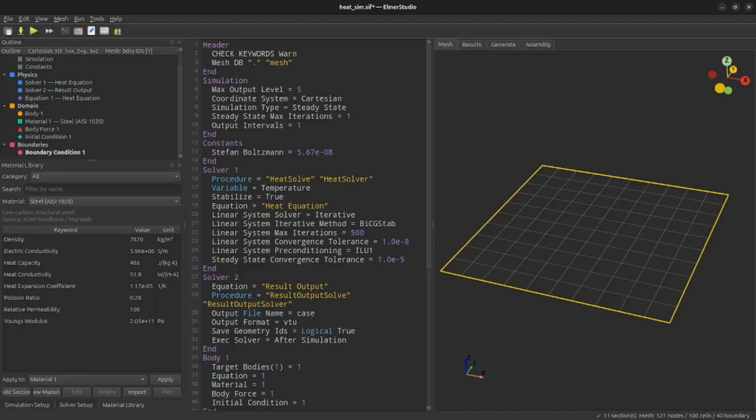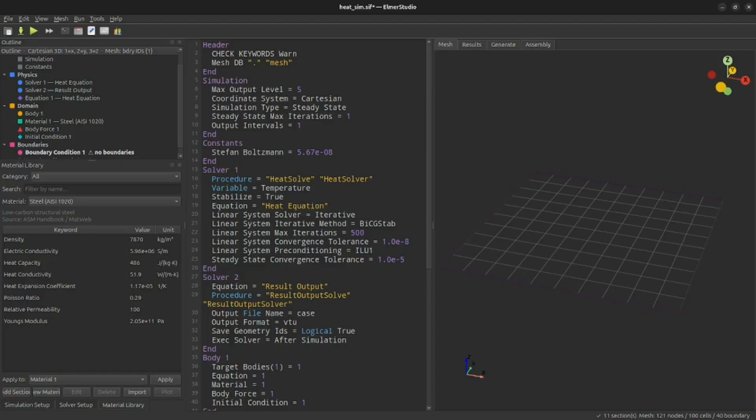If you left click on the boundary, you can actually select the boundary. If you hold down Control and left click, then it gets deselected. So let's see how we can actually split this or get 4 separate boundaries. There are a lot of options, so I'm going to select the boundary again.